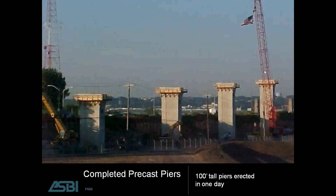The erection rate is rapid with precast piers. These piers, the 100-foot tall piers, were erected in 1 day. Of course, the starter segment has to be placed the day before and grouted into place, and that grout has to achieve strength before proceeding with the placement of each segment. But it's relatively quick construction, and it facilitates and expedites the job.